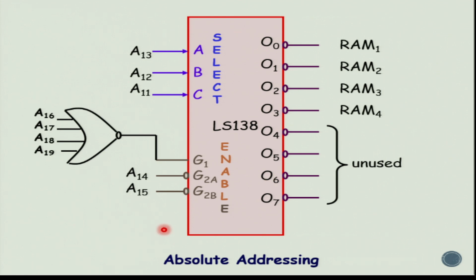So this is how you can connect a memory chip to 8088. We saw with an example how to connect an 8K chip. The first step is to decide on the number of chips. The second step is to do the memory mapping. The third is to design the decoding logic. We'll stop with this in this session. In future sessions, we'll see more examples of how to connect memory chips to 8088 as well as to other processors.